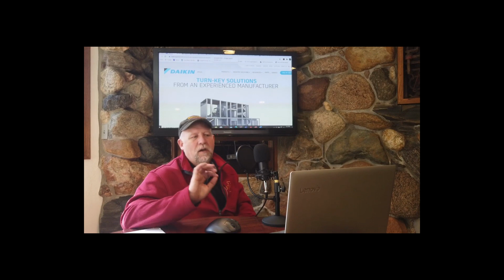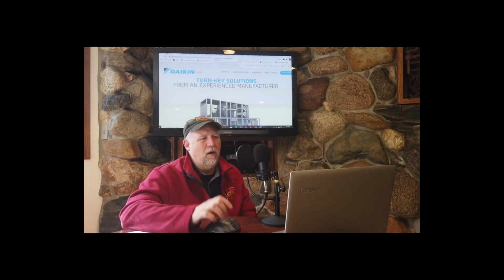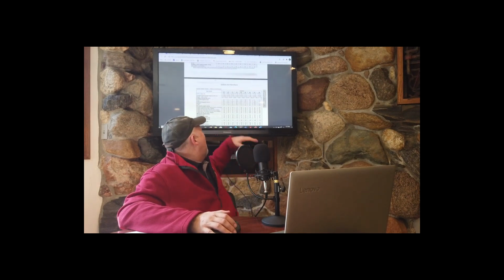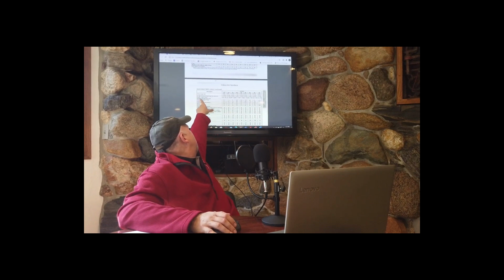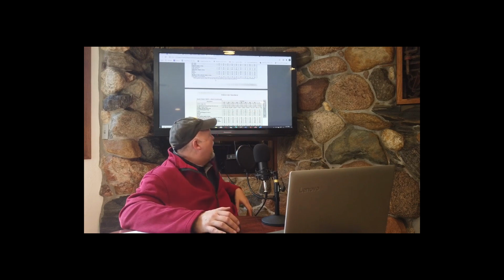So, I know it's a long time until you're picking air handlers for your final project, but make sure to note that someplace in your notes, remember it, and come back to it. Here's how we get the overall length of the air handler. So first, we get the height and the width. We're just going to use a 40,000 CFM air handler, and it tells us the height is 110 inches high and the width is 136 inches wide.